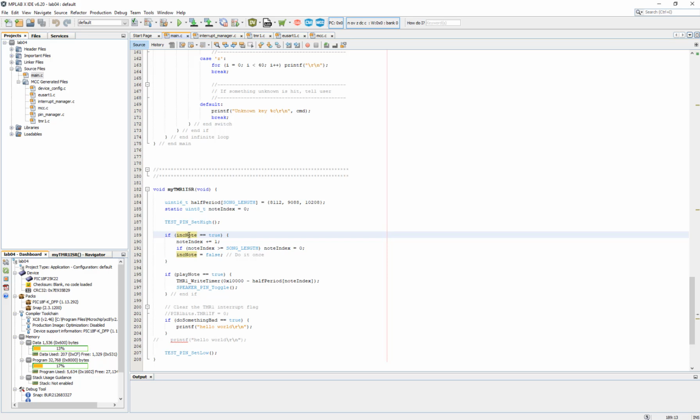If you start running, you power it up, you have the code downloaded to your microcontroller, it's going to start calling that interrupt function every 4.1 milliseconds. It's automatic. It's always going to do that because it's called an interrupt. It's going to interrupt whatever is running in your main code. It gets into here every 4.1 milliseconds for the first time.